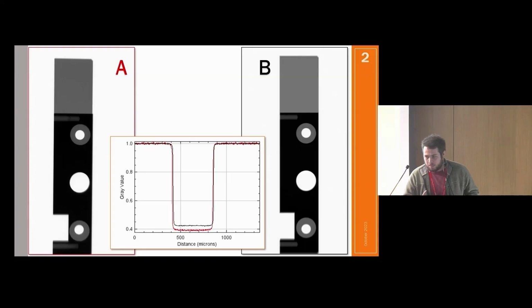I'll give you a hint. One of these is a CAD model. The actual simulation is B, and you can kind of see, I don't know how easy it is to see on these projectors, the screws are too perfect, whereas on A we have some filled cavities. The interesting part is that we found out that the manufactured part is slightly out of spec, because we're having some larger edges here compared to the backplane.